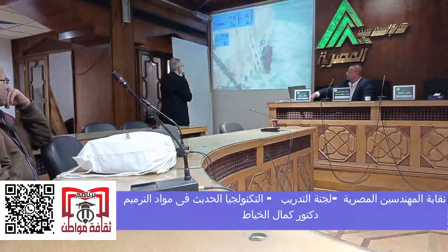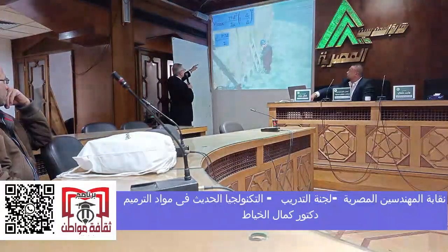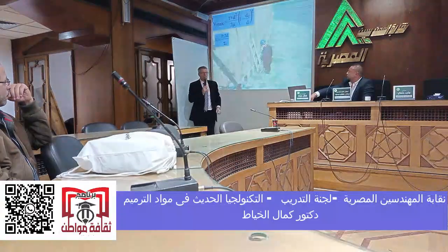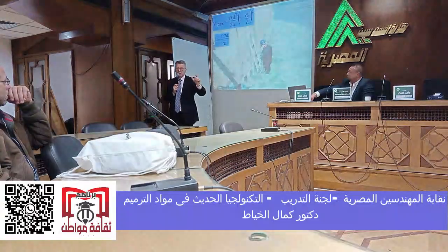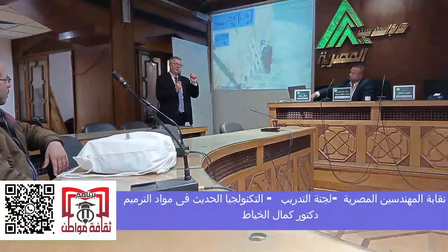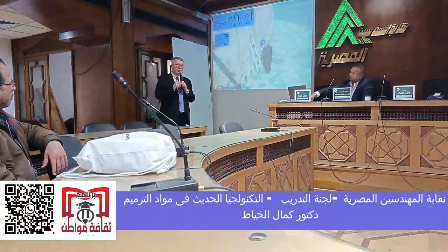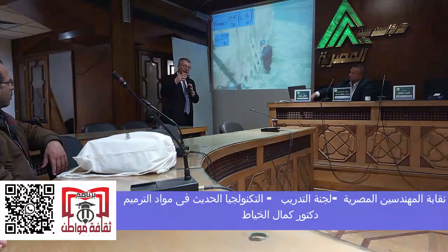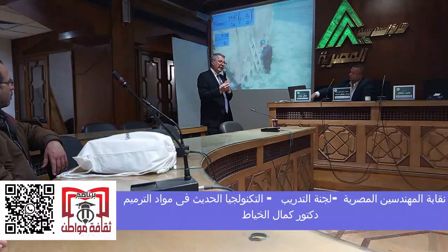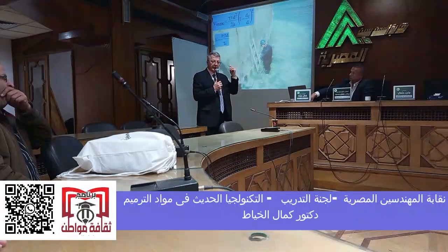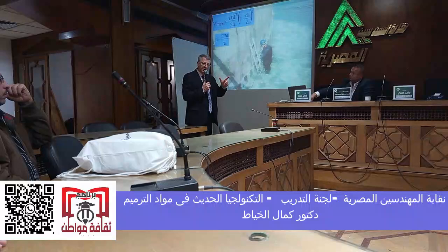And the other parameter that is important here is tau zero. Tau zero is the yield stress, and the depth of penetration is going to be dependent on 1 over tau zero. So if you reduce yield stress, you make your grout very flowable, it's going to penetrate deeper. If you make it less viscous, it's going to go faster. So I'm sure that the repairman is thinking about that as he's injecting.